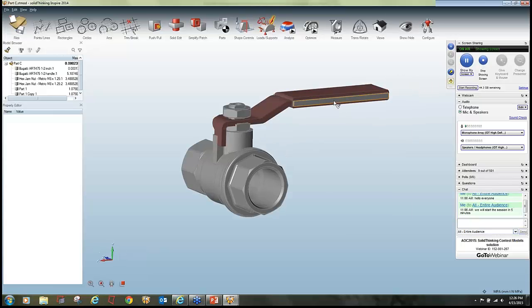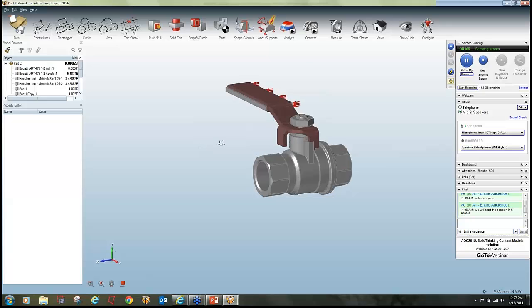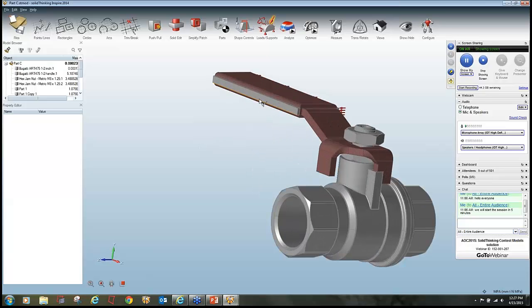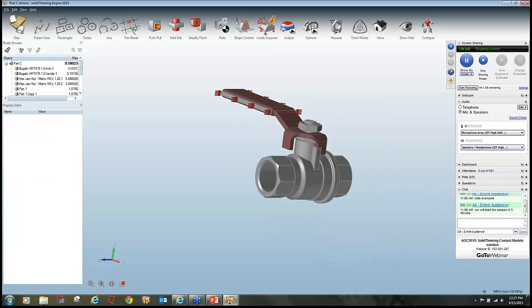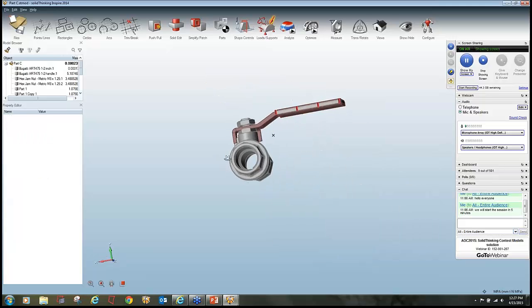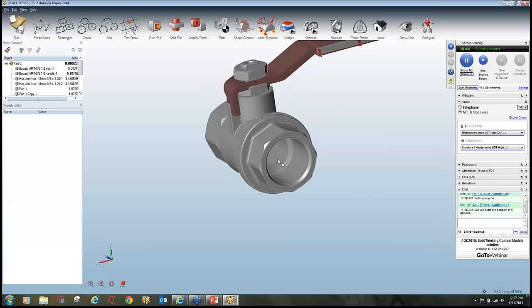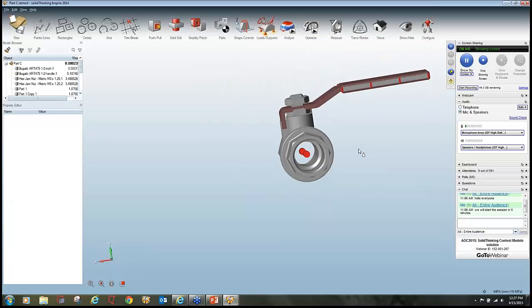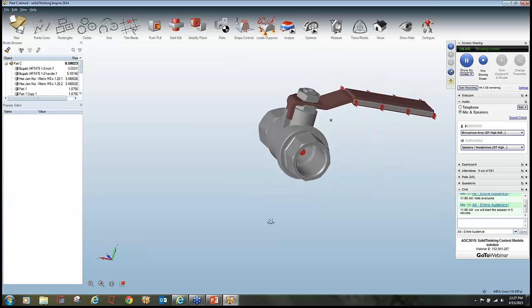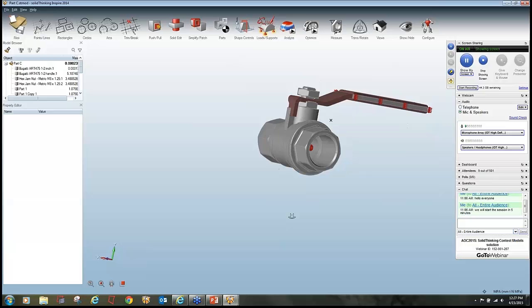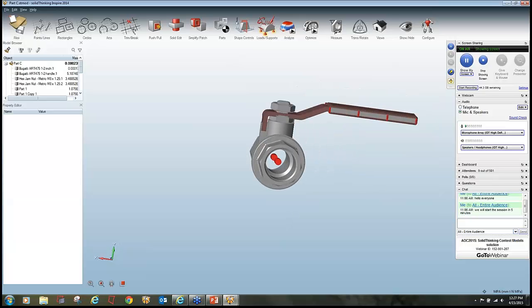Apply the forces of 200 Newton such that it resembles compressive loading. Apply constraints fixing all the degrees of freedom on both the bolt locations. So I have to create one more constraint.